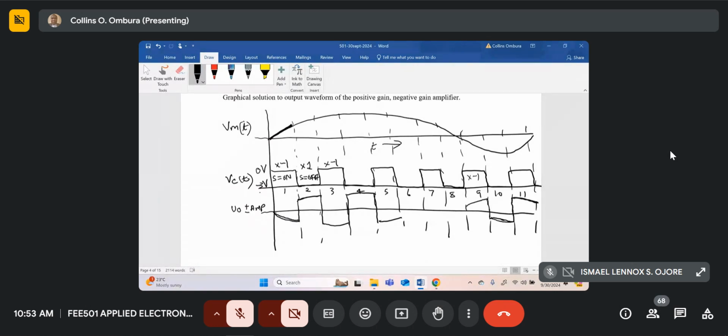But the last interesting part, so this is how the modulation is done. The modulator multiplies the input with a negative or a positive in correspondence to the frequency of the switching signal.